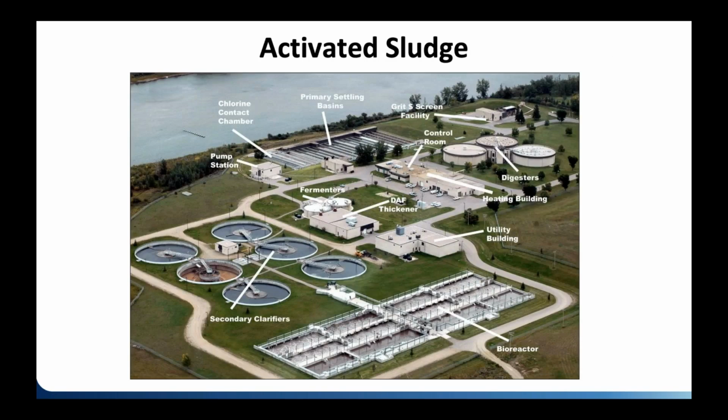So this is your typical activated sludge plant. Right up here, you've got the screening facility. Then you have primary settling, where you're settling out some of the sludge. Then water comes down to the bioreactor, which is just aeration tanks. All these aeration tanks are full of nice, dark, really dingy water. The whole goal is to get the bugs as concentrated as possible, and to get the food, the bugs, and the oxygen together within this aeration basin as best you can.